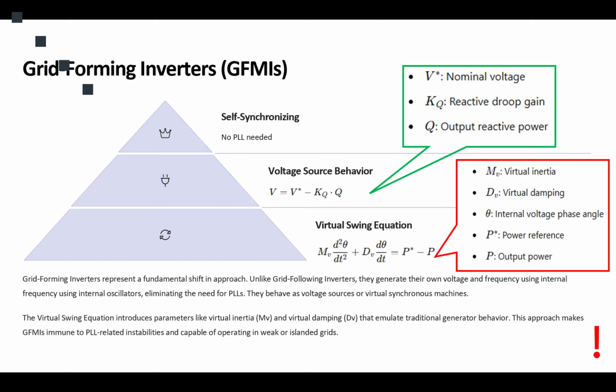So we have a short circuit in the grid, or any kind of fault in the grid. What the inverter sees at its terminal is a fluctuation in voltage and frequency when there is a fault in the grid. The control system is designed to automatically follow those fluctuations. It has a reference. It doesn't understand that there is a fault.